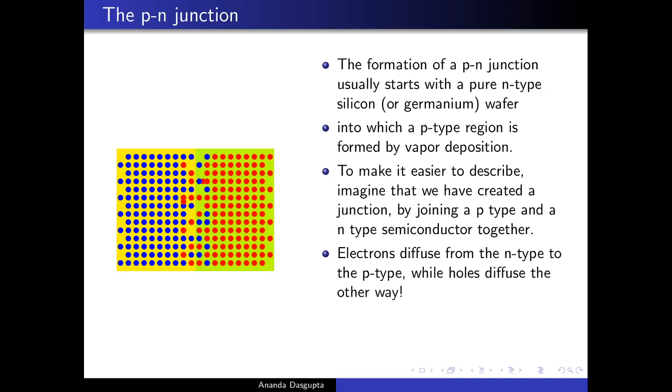The same does not happen here, thankfully, because if the same thing had happened here, you would have ended up with all the electrons and holes diffusing all over the place, of course meeting each other and killing each other by recombination in the process, and ultimately you will be left with either an intrinsic semiconductor effectively, or maybe an N type or a P type, depending on which particular side was doped more. But that would be rather uninteresting. All this trouble that you're going through of creating a P type and an N type and putting them together is simply wasted, or would have been wasted if this were to happen.